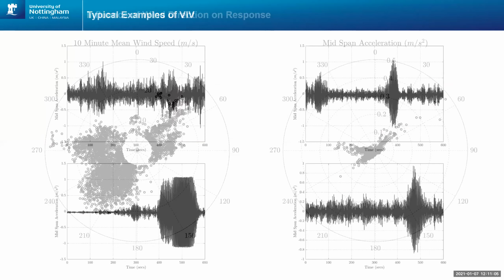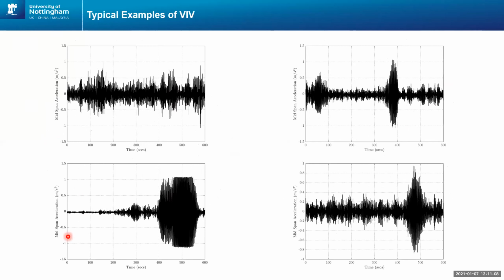Now, when we look at those records in more detail, these are just 4 typical records where those responses are very large. And this, we believe, is due to vortex-induced vibrations. The important thing to note is the large response occurs just in very short bursts. The longest is maybe 1 or 2 minutes in this record here.